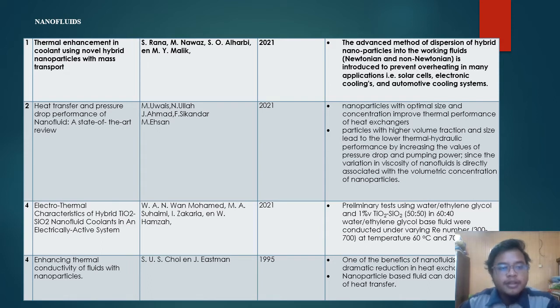Heat transfer and pressure drop performance of nanofluids, a state-of-the-art review. The nanoparticle with optimal size and concentration improves the thermal performance of the heat exchanger. Particles with a higher volume fraction and size lead to lower thermal hydraulic performance by increasing the value of pressure drop and pumping power, since the variation in viscosity of nanofluid is directly associated with the volumetric concentration of nanoparticles. The third one is